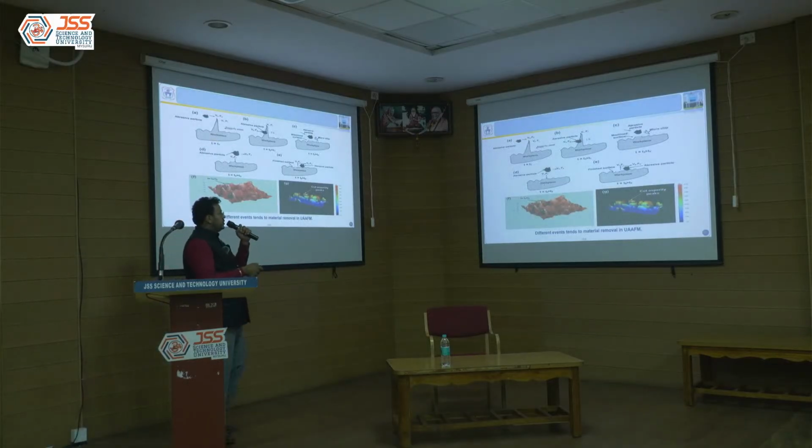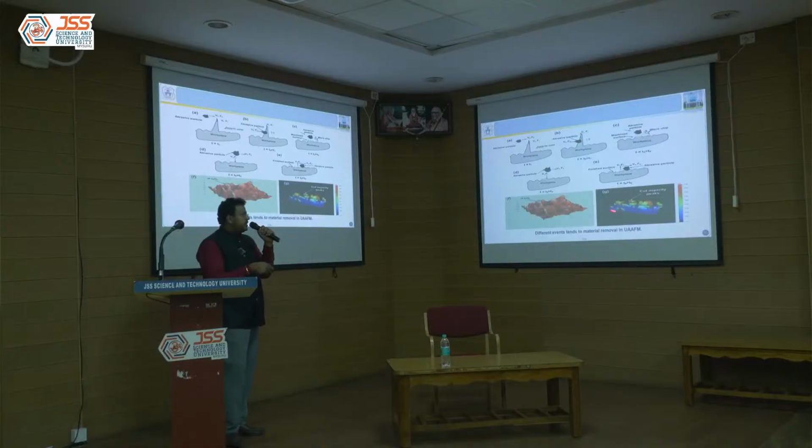Yeah. So you can see the abrasive hitting the asperity at t equal to t1 when you are following the sinusoidal cycle, and at different time intervals you can observe that the abrasive particle is actually participating in the asperity hitting, compared to simple AFM. That is also observed under the microscope and also atomic force microscopy, how the tiny chips are cut on a surface.